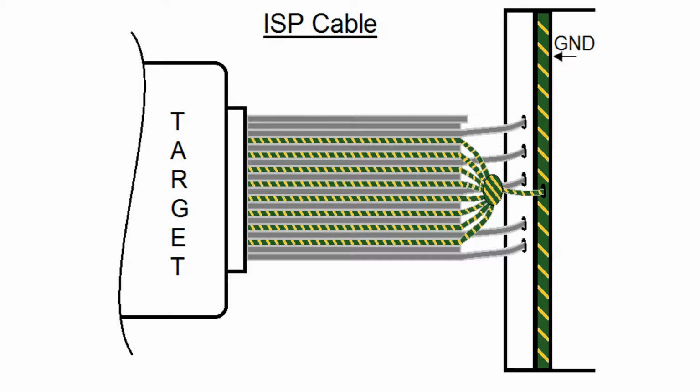Reprogramming signal functions is provided electronically in accordance with the device type chosen by the user. This allows usage of the same 20-wire ribbon cable for programming a variety of target devices. Each signal line in the ribbon cable is interspersed with a ground wire. This configuration reduces glitches on the ISP signal lines, improving signal-to-noise ratio.